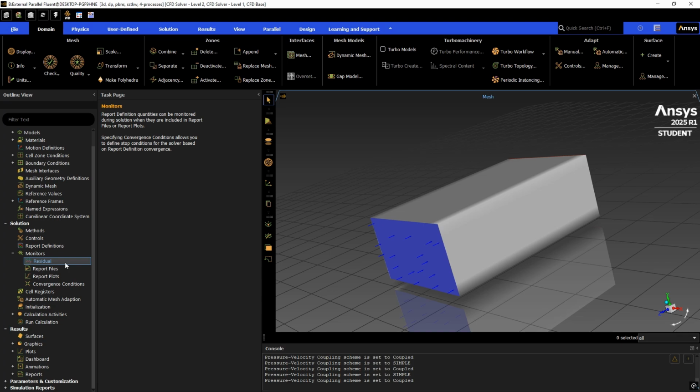So I told you about the convergence situation, but there is a very important question here. If you study CFD and if you go further into this field, at some point you will probably come up with this question, and I am going to give you an answer right now, and the question as well. So the question here is, if your solution is converged, but you used the wrong viscosity model, then is your solution acceptable? Does your solution necessarily have to be correct? And the answer to this is no.